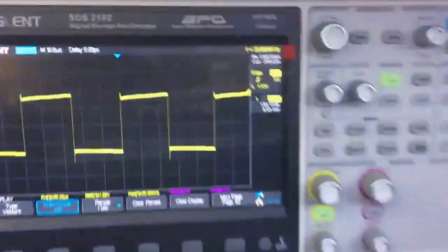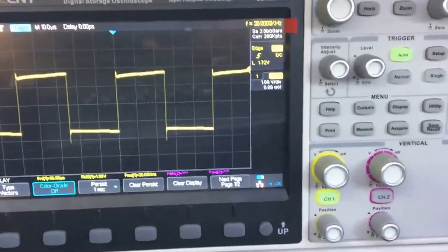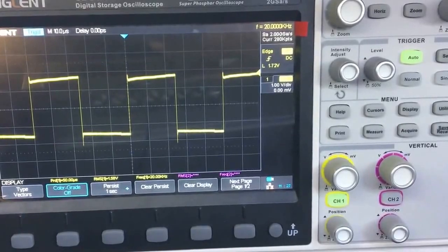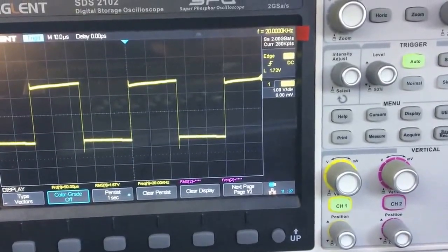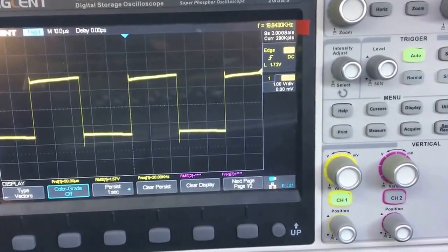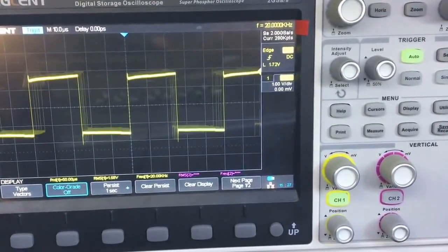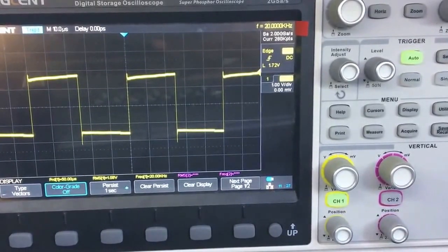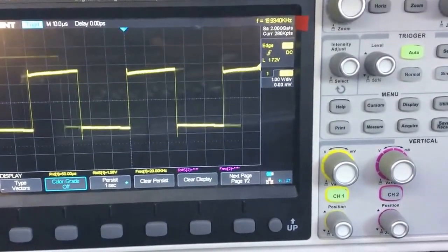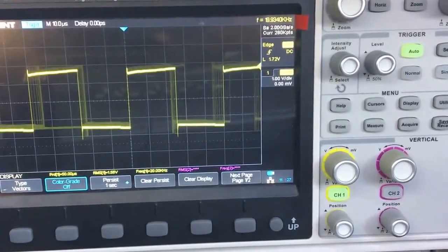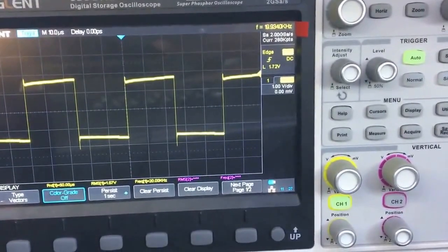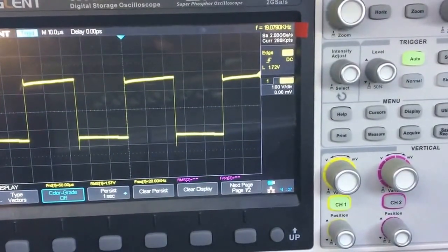And if I look on the scope, I'll do the same thing. You might see a couple of little glitches when it goes through some ranges where it steps, but generally it's pretty good. I mean, it's gone right down almost. There we go, see a little glitch there. Right at that point there. So between 250 and 240 it's doing that. And I know there is a range change just there, so I'm not too worried about that one.